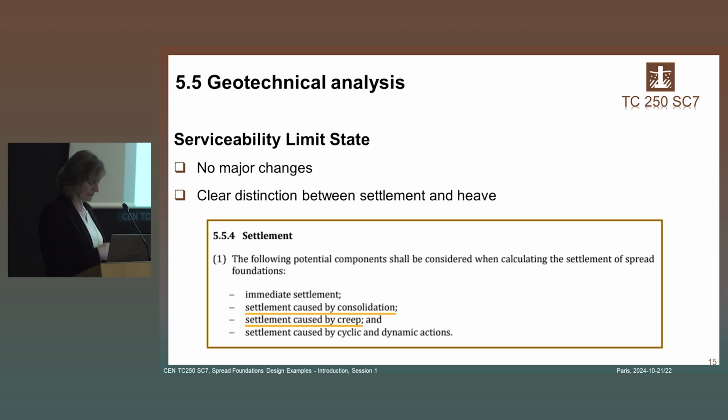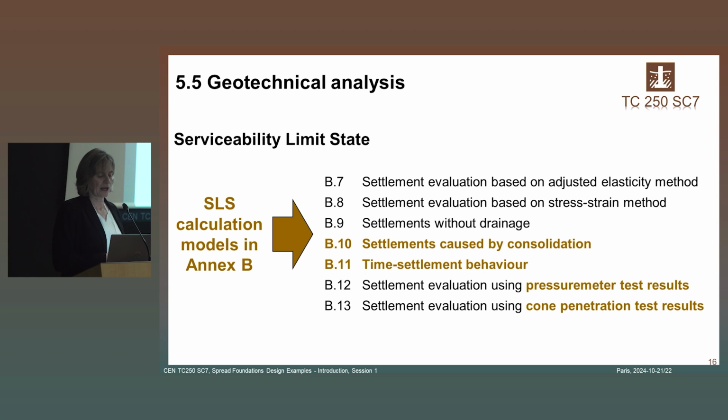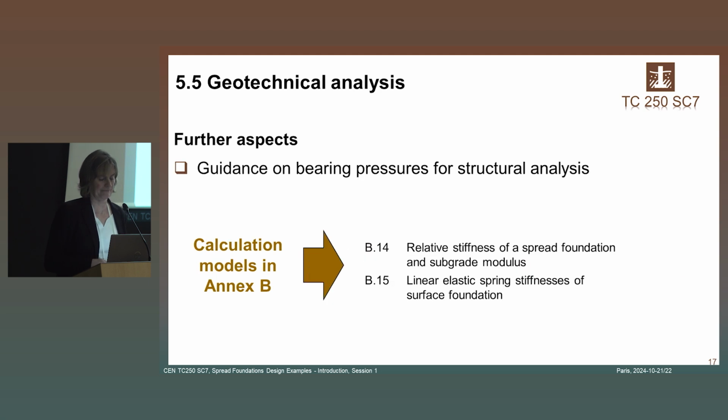Let's go over to the serviceability limit states. Here it is clearly distinguished between settlement and heave. Also, settlements caused by consolidation and creep are considered. And for the serviceability limit state, there's also a lot of additional calculation models provided in the annex. For example, settlements caused by consolidation, the time settlement behavior, or also settlement evaluation based on field test results like pressure meter test as well, and also CPT results.